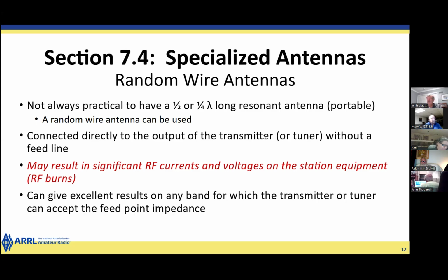But getting back to this, you're going to have a lot of problems if you use a random wire antenna. You could and probably will have a lot of problems with stray RF in the shack, and I would not recommend doing anything like that. Even though they say here you can get excellent results with it, I don't think it's worth the effort.